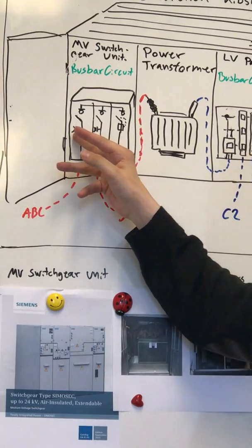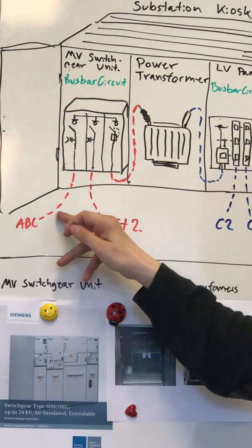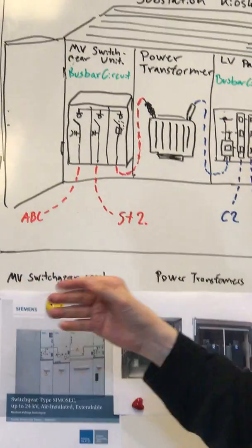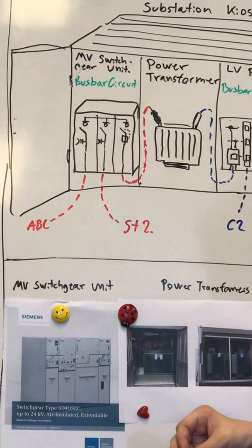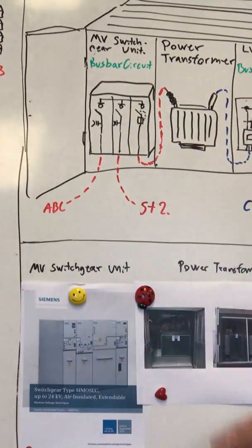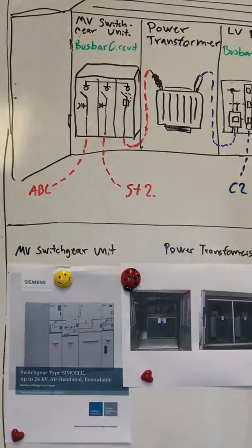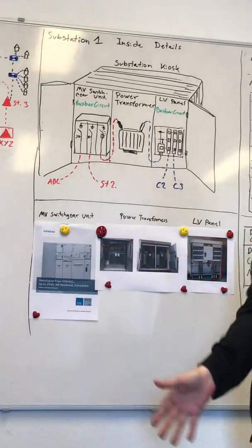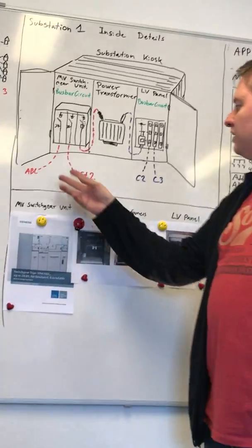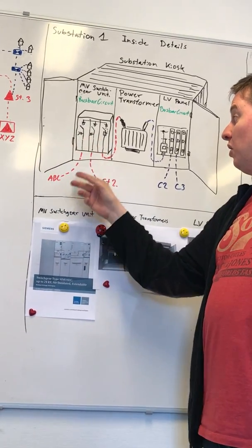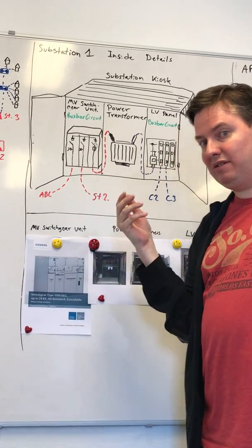And what that thing does is, if this cable gets a short circuit, that means someone dug into it or something. Or maybe someone just drove into it and broke it. Yeah, if you drive into a substation, but the cable's in the ground, so they cannot drive into that. Low voltage, they can drive into the cabinet. But if something happened to that cable, typically someone dug into it, then it will short circuit. And then they can see on these indicators which cable was actually